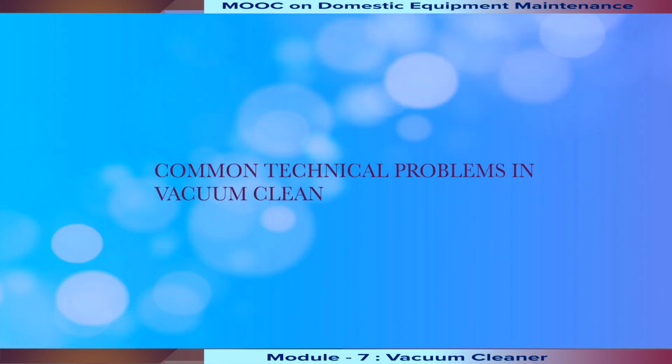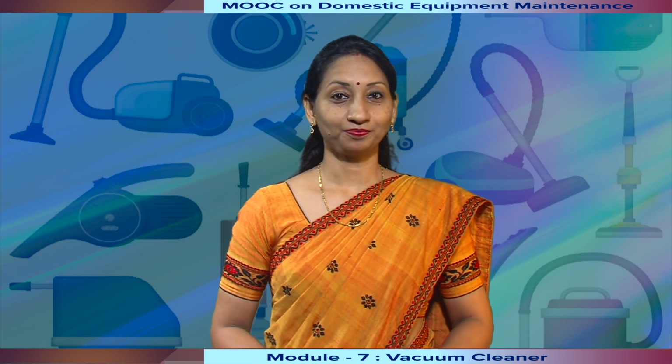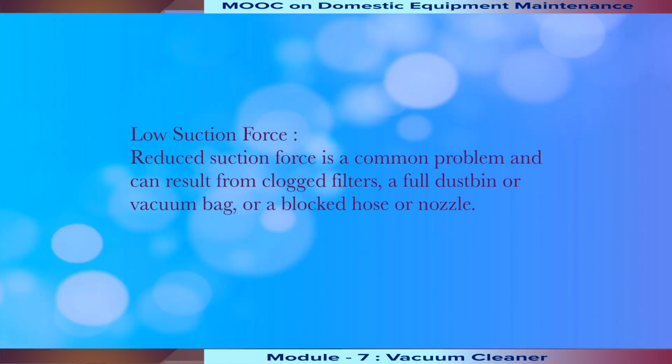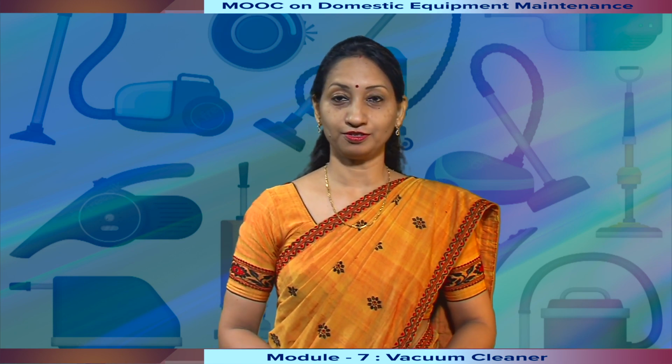Dear learner, let us now try to understand the various technical issues or problems commonly encountered in a vacuum cleaner. Some of the common technical issues are: number 1, low suction force. Reduced suction force is a common problem and can result from clogged filters, a full dustbin or vacuum bag, or a blocked hose or nozzle. To troubleshoot this issue, clean or replace the filters.